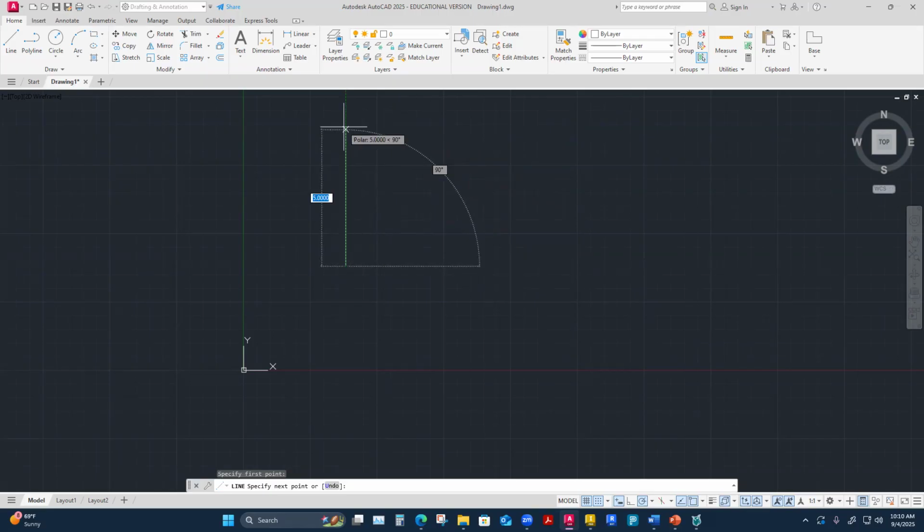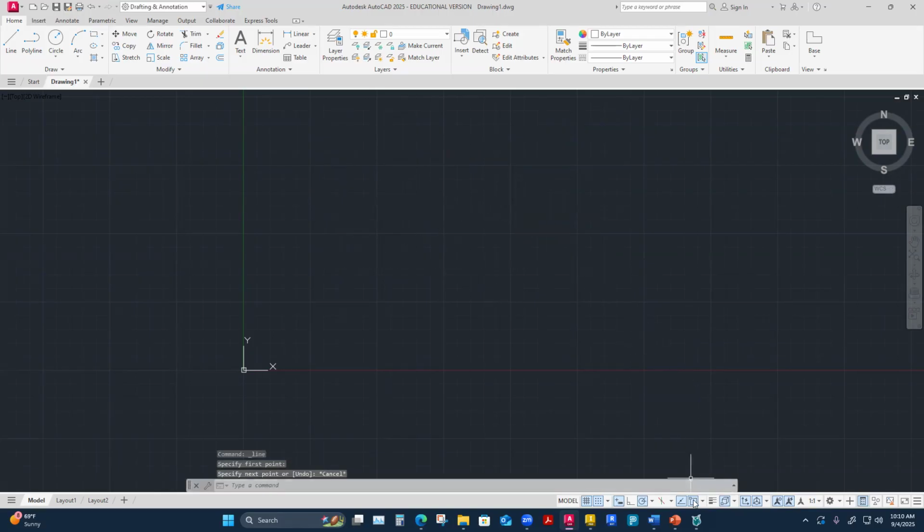So let me turn that off and show what it looks like differently. This is me with the functionality that I like to have on. I've got dynamic input on. I've got polar snap tracking on. And I've got some particular increments set. So let me turn those off. Where those are is on your status bar down here. And I can just turn off those tracking. So if I turn off this one, object snap tracking, and let's turn this off too. Maybe that's all I have to do. Let me look at my line now.